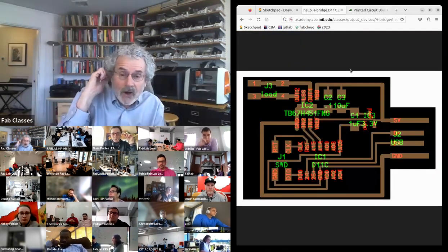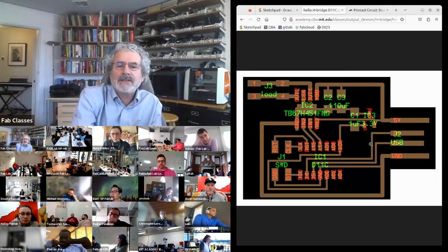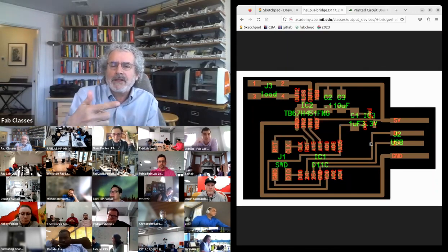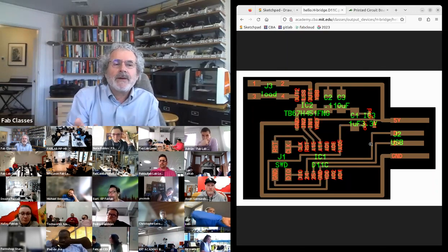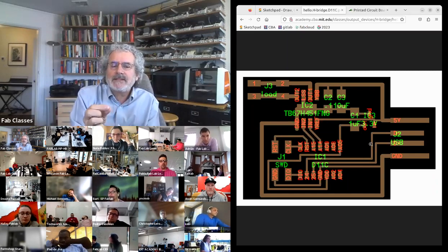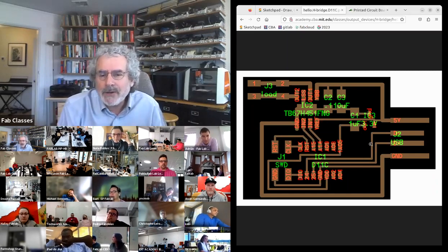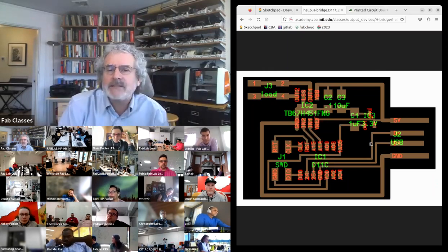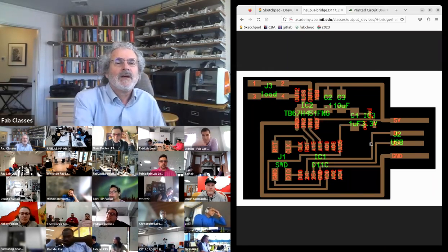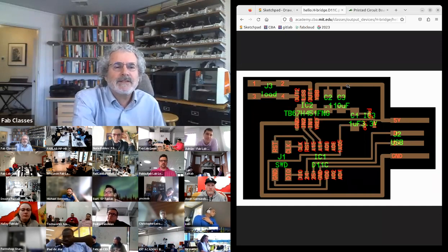Power is I squared R. There's some resistance in the traces. Once you start pulling more current, you care about this. If you use a skinny trace, it actually will get hot. The dissipation in the trace becomes noticeable. So when you start pulling more current, you typically use fatter traces.